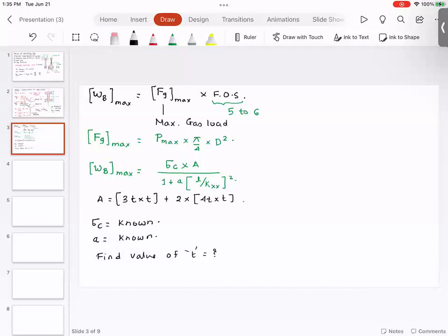Many times it would be tested by some lab, like Underwriters Laboratories, or an equivalent lab, or a mil standard. And that will tell you that this part has 10,000 hours of life. So this will not break under the regular operating conditions for 10,000 hours. That tells you what cycle it can sustain.